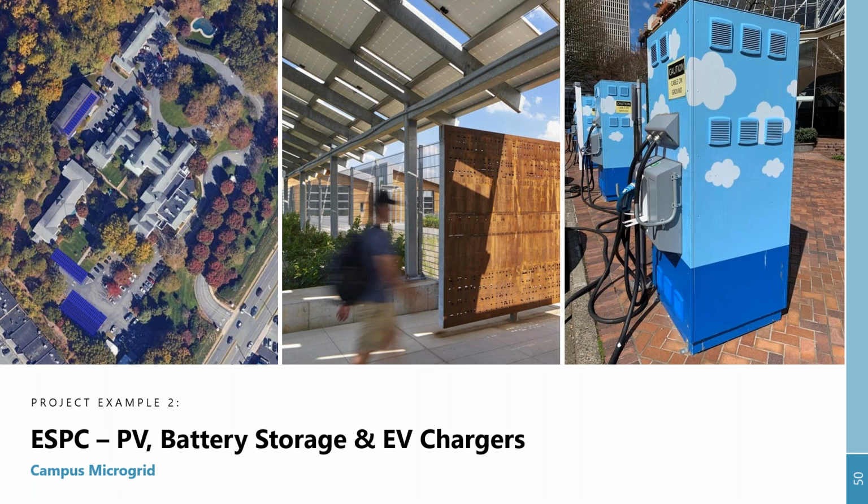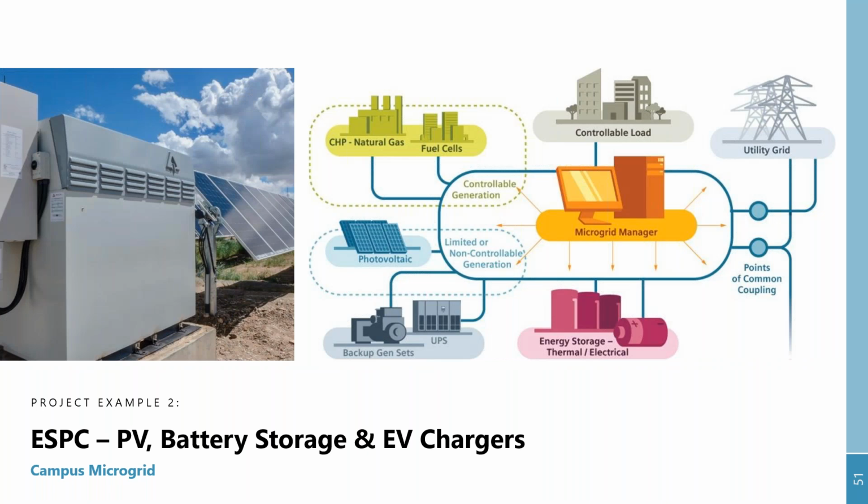Yeah. So when we visited the site, we did the study for the PV. We had a couple of meetings with the contractor, and we came up with an optimum solution for the PV system. As you can see, the blue ones represent the PV array. So the existing distribution system has the utility and a generator with a single automatic transfer switch. The generator is able to power the entire campus. By adding PV battery storage, we will help with reducing the consumption of the fuel, the diesel, when needed.